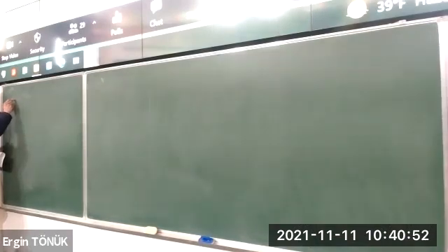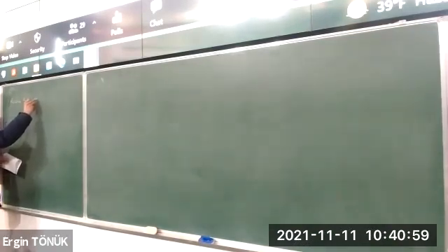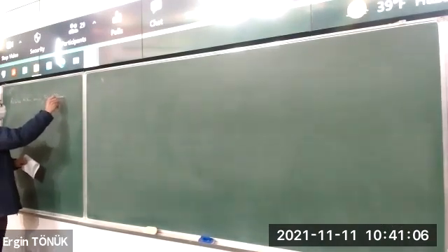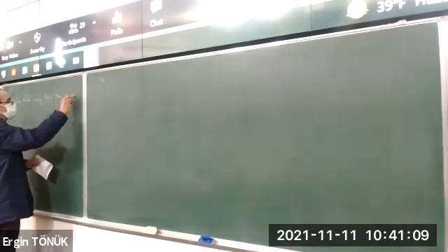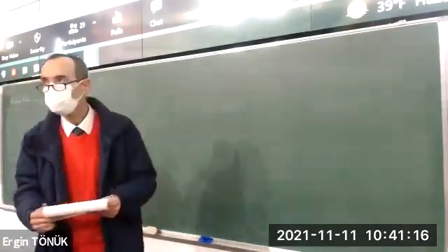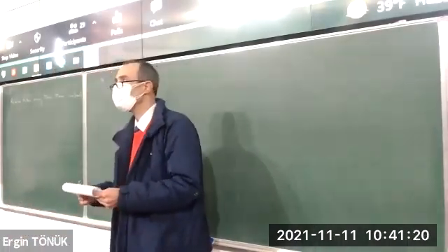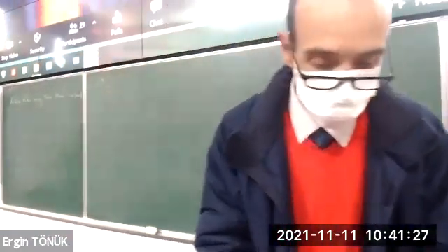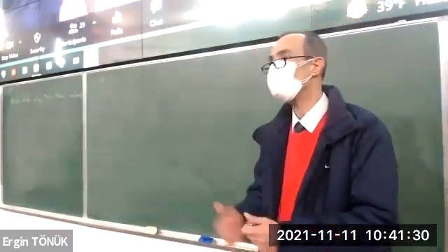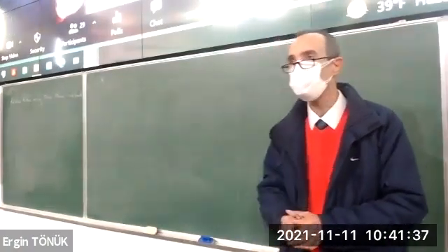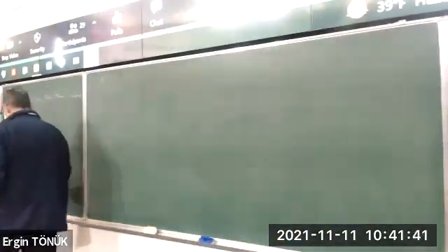motion, three planes and one is fixed. Actually, the 2 moving planes are now 2 cranks, and we also have the fixed plane. Now, an important simplification in plane motion is the rotations are additive. That is, if you think in terms of dynamics, x, y, z, all the rotations are about the z-axis, which is perpendicular to the motion of the plane. So that's an important property.